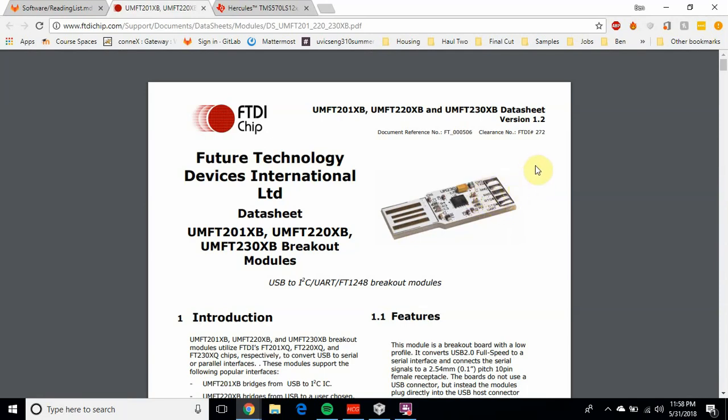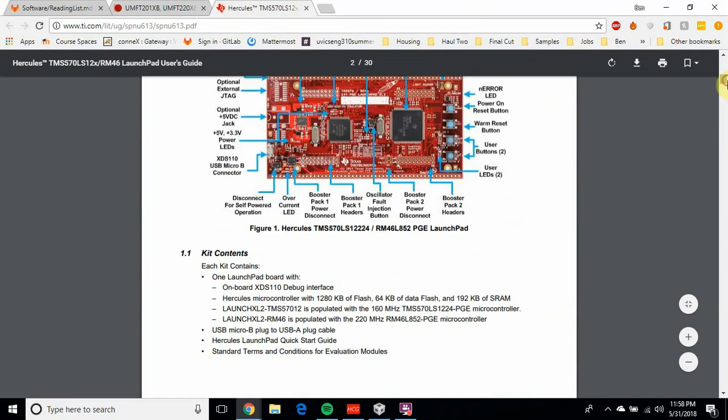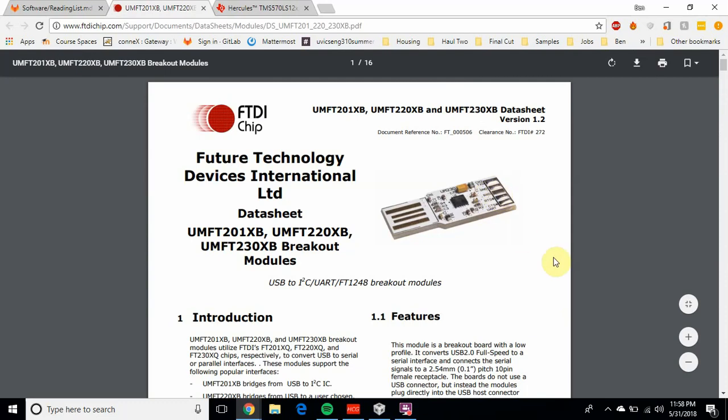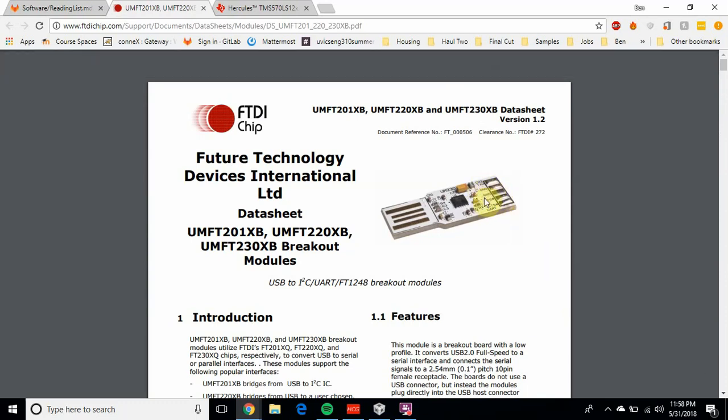What we do then is we plug wires into these different little inputs, the female connectors, and then we can plug those wires onto the board itself, onto those headers, which you can see on the board here. So essentially certain pins here are going to connect into certain pins here. The 3 we're going to be using today are known as TX, ground, and RX.